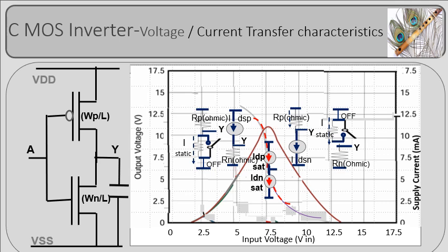Region 1, for input less than transistor threshold voltage, the output is at high level. Region 2, for input at VIL, reaching NMOS threshold voltage, NMOS starts turning on and output will be at VOH. The transfer characteristic represents a slope of unity and the output voltage starts decreasing. Region 3, rising input voltage equals the falling output voltage at the gate threshold VTH point. Inverter with both transistors operating in saturation mode conducts maximum current IDD. The inverter with high gain starts acting as an amplifier.